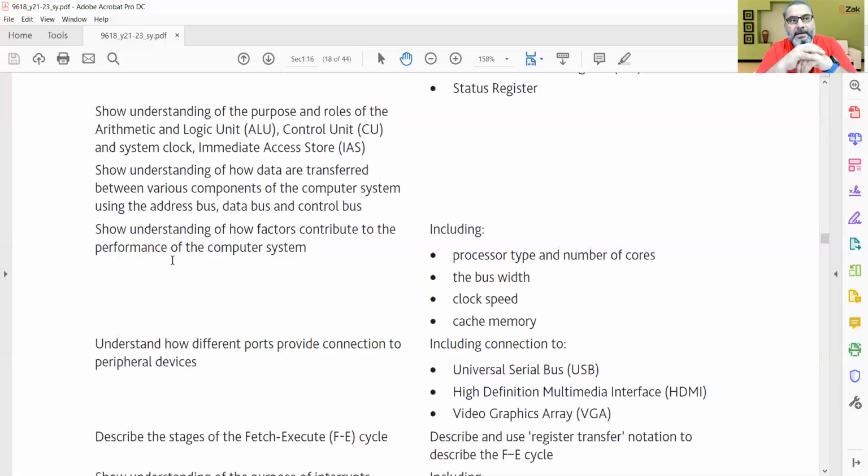All right. But as we know, if you increase 1 bit, the capacity doubles. For example, in 1 bit you may have 2 values, in 2 bits you may have 4 values, in 3 bits you may have 8 values, in 4 bits you may have 16 values. Similarly, if it is 32 bits, you may have 4 GB, in 33 bits you may have 8 GB, in 34 bits you may have 16 GB, in 35 bits you may have 32 GB, and similarly with every increasing bit, the capacity of the RAM that the microprocessor can access gets doubled.